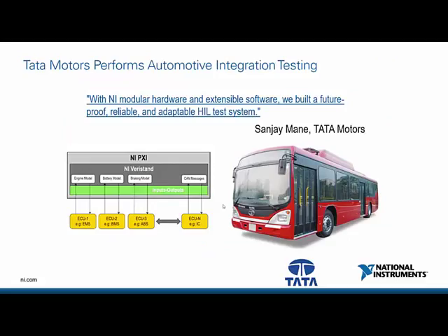And this is another really good example of customers understanding the value of VeriStand. So that, again, this is a smaller integration system, but it was an application that required testing of 6 ECUs. And using VeriStand, they were able to break up the system, the physical system, into different submodels and test all 6 ECUs essentially with one PXI system. And it enables them to extend the functionality and the performance of the HIL system as their needs changed.